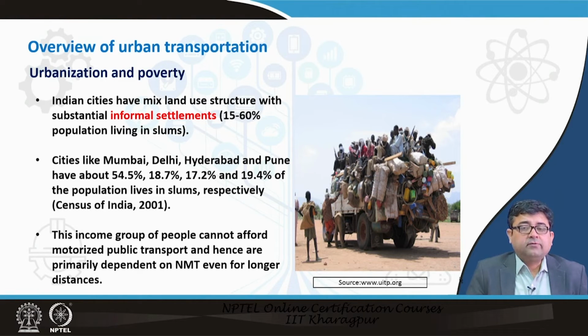And now suddenly if there are no sidewalks or there are no footpaths alongside these roads, or there are not enough buses, if a bus comes only once an hour, what happens is the people who cannot afford vehicles are now at a disadvantage. Now, you had a 2-lane road where they could maybe cross safely. Now, with the 4-lane road, the crossing of pedestrians becomes unsafe, and so the people who are accessing job locations from one side of the road to the other side of the road now feel unsafe.